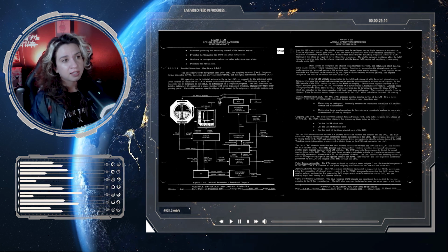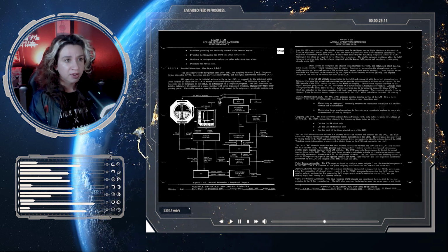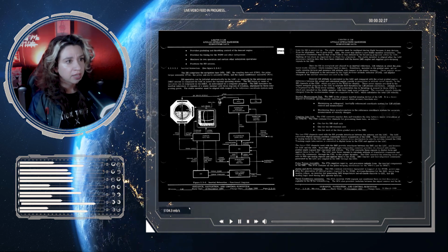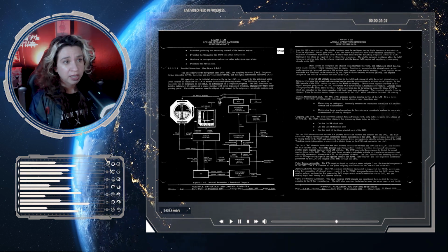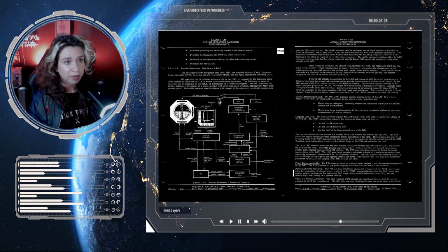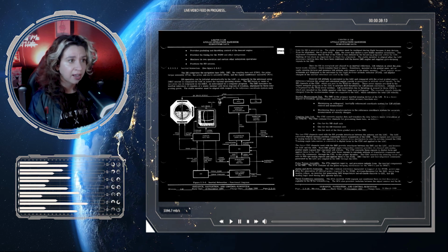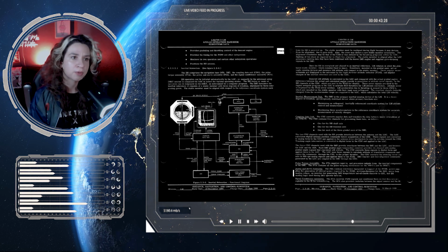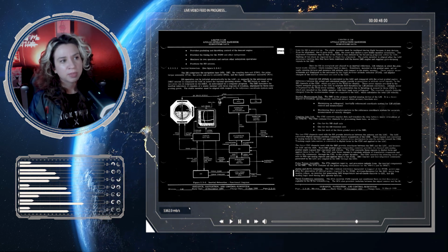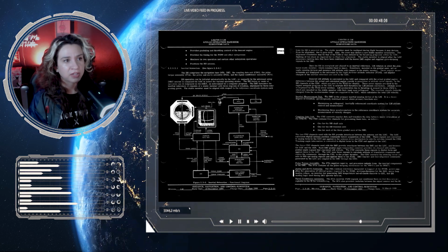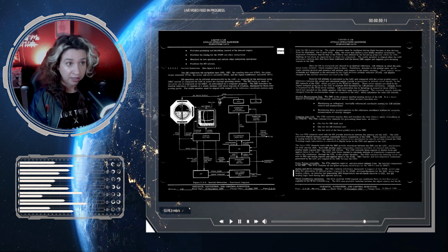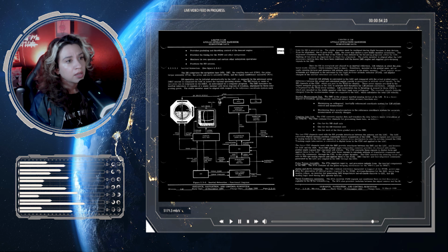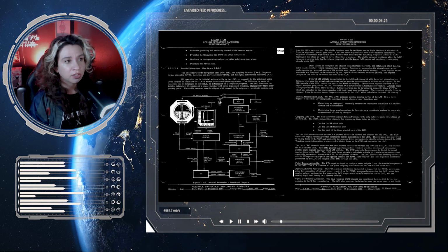Once the ISS is energized and aligned to the inertial reference, the LM rotation is about the gimbaled stable member, which remains fixed in space. Resolvers mounted on the gimbal axis act as an angle sensing device and measure LM attitude with respect to the stable member. These angular measurements are displayed to the astronaut by the Flight Director Attitude Indicator, or the FDAI. The angular change of the inertial reference is sent to the LGC.